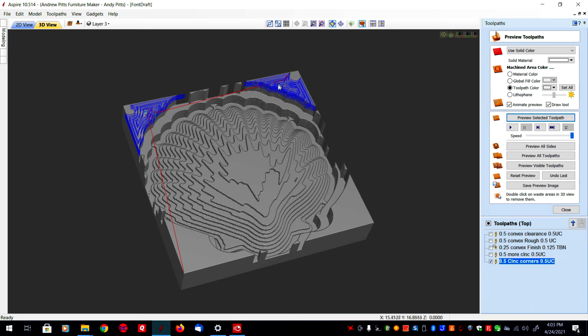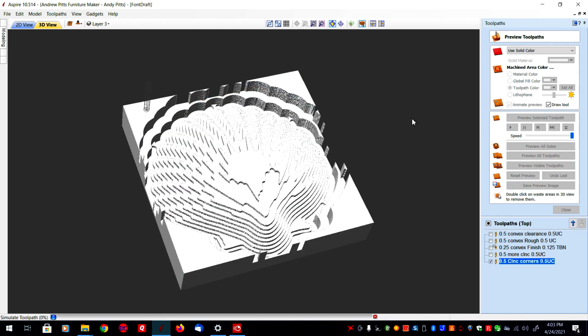And with that, I actually was very careful not to cut where the hold down screws were. Even though I had reset the hold down screws by 3/4 inch, I didn't want to take any risk of running the end mill into the steel of the screws. So that's why I made those big clearance holes, and that's how that looks.